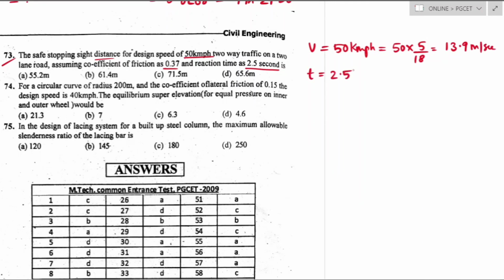T is the reaction time, that is 2.5 second, and F is the coefficient of friction, that is 0.37.